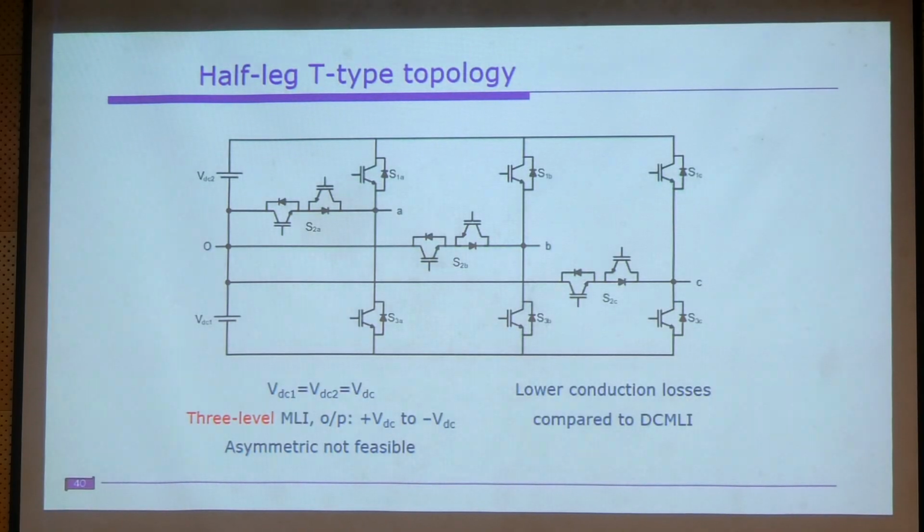Alright. So this is commonly used and the best alternative for the diode clamp and the active neutral point clamp, right? So why is it an alternative? You can see that the number of switches is less, the gate driver requirement is also less, and it will also reduce the conduction periods. Earlier, two devices were on the top and two on the bottom, so now you have only one device.